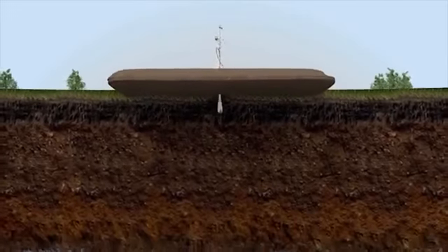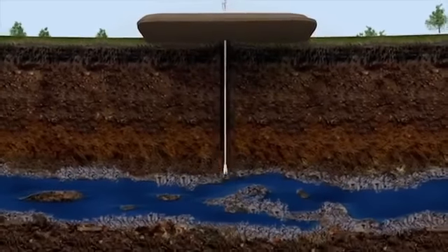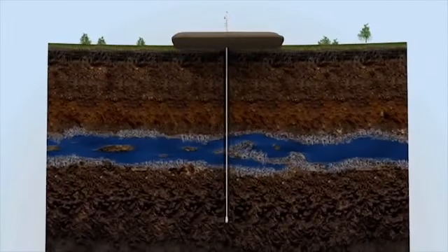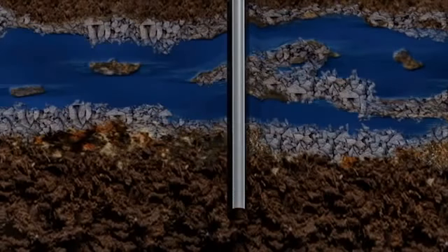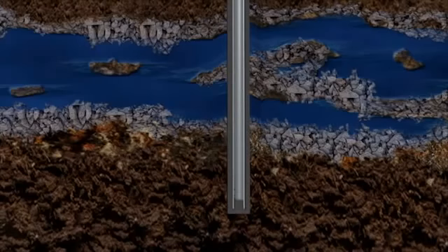The initial steps are the same as for any conventional well. A hole is drilled straight down using freshwater-based fluids, which cool the drill bit, carry the rock cuttings back to the surface, and stabilize the wall of the well bore. Once the hole extends below the deepest freshwater aquifer, the drill pipe is removed and replaced with steel pipe, called surface casing. Next, cement is pumped down the casing. When it reaches the bottom, it is pumped back up between the casing and the borehole wall, creating an impermeable additional protective barrier between the well bore and any freshwater sources.